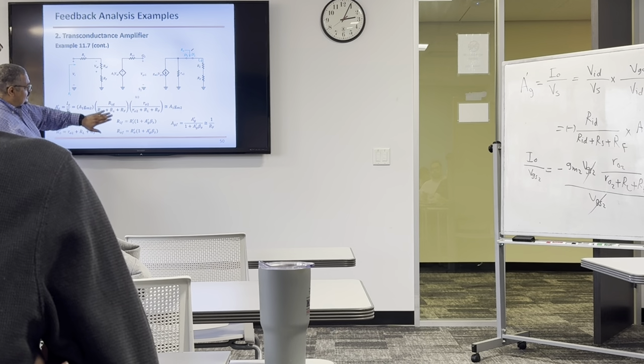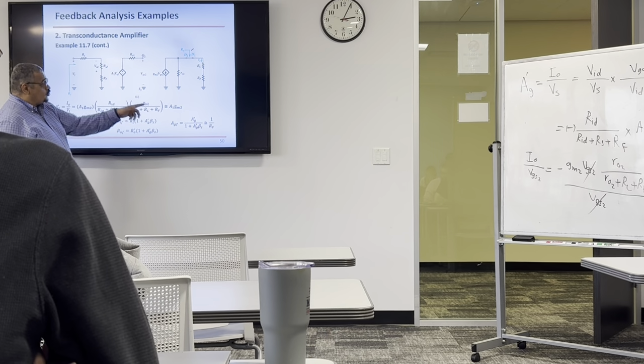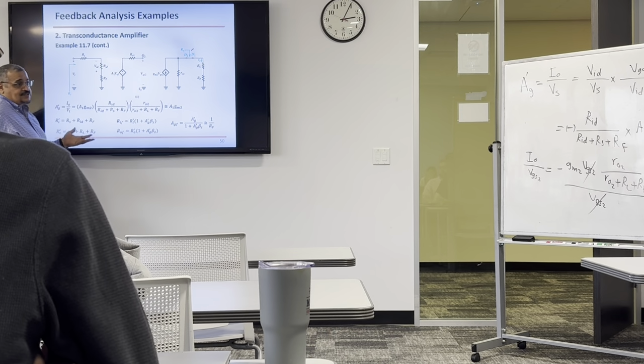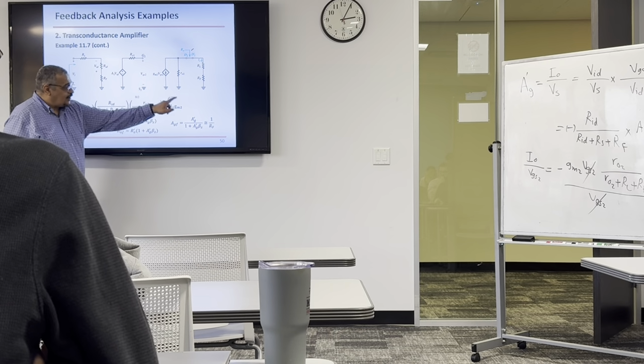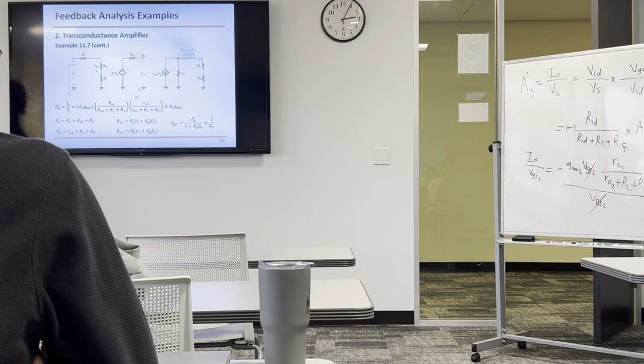In this case, this is going to vanish, right? And if this is deleted, Ri differential could cancel, and this becomes 1. If RO2 is very large, which is the case, it's 200, 500, 300, so this is going to be much larger, then you remove this, then you cancel. So approximately this is A1 times GM2.